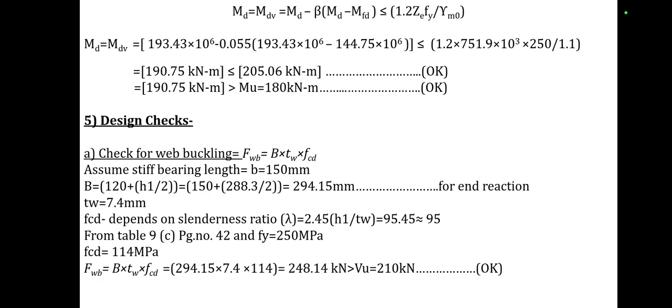Then from table number 9C, page number 42, and Fy is equal to 250 MPa, our value of FCD is equal to 114 MPa.